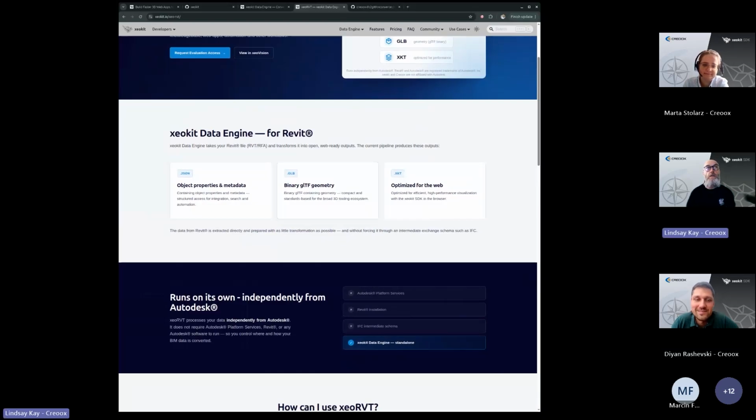Following on from that, we also have a new tree view component. One of the philosophies of xeokit is customizability, the ability to extend it and customize it as you need. So we have a new tree view plugin, which is deeply customizable. Rather than relying on a fixed BIM tree, developers can generate their own navigation structures by instances, families, levels, or any other hierarchy, and connect them directly to 3D selection, visibility, and property inspection. This is an example of how xeokit's semantic data model enables highly customized BIM user experiences beyond traditional viewers. So we're not just coupled to IFC.